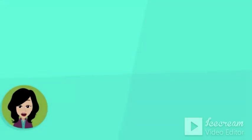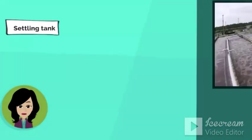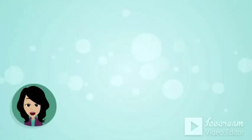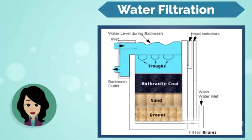The most commonly used settling tank is the rectangular sedimentation tank, which has an effluent weir structure visible above the fluid surface. These rectangular sedimentation tanks are called settling tanks. As soon as the water leaves rectangular tanks, it undergoes water filtration, which is the process of removing suspended solids and contaminants from water in a granular media filter.